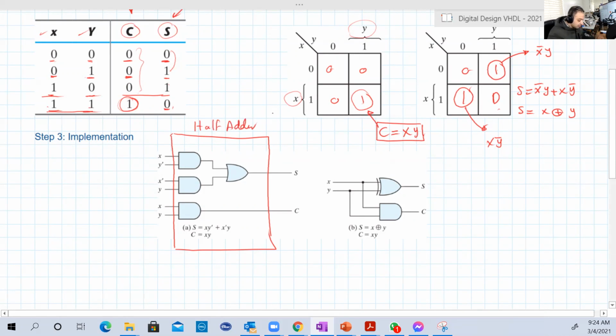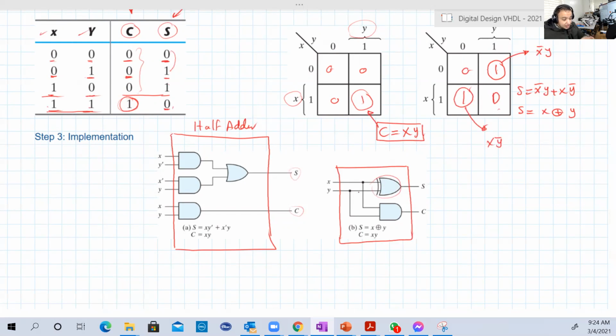And do you know that there is an AND gate that has X and Y, and there is a sum bit which is X XOR Y. Or you can implement it also using a symbol we have for the XOR, because basically we can do the XOR using one circuit. So you can design a circuit using transistors and so on. To make an XOR circuit, you don't need to do two AND gates and one OR gate, although both are acceptable,